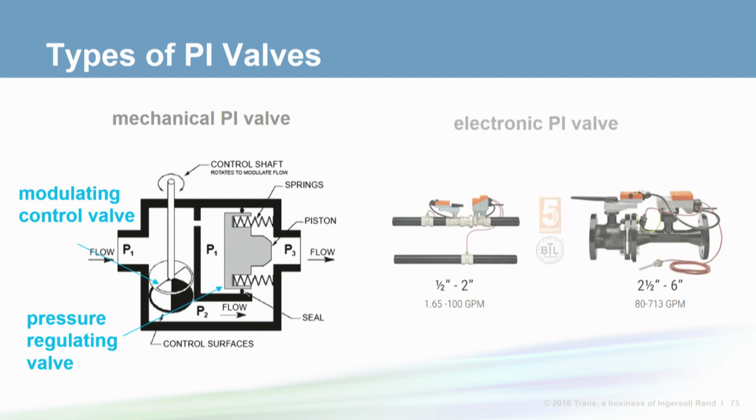On the other hand, an electronic pressure-independent valve doesn't actually maintain a constant differential pressure across the control valve surface. Instead, it achieves independent control similar to a pressure-independent VAV valve. It includes a flow meter in series with a standard control valve. It then calculates the instantaneous flow and pressure across the valve and continuously recalibrates the control coefficients to provide stable and accurate control.